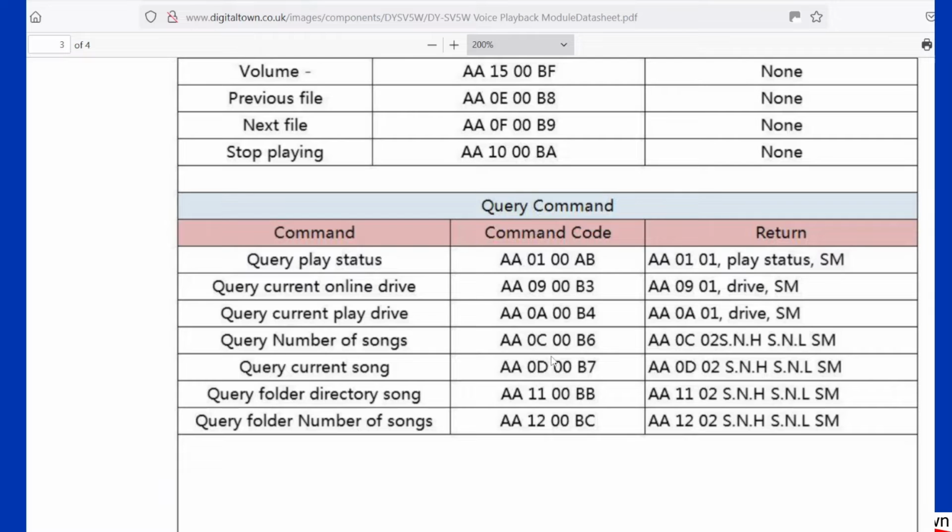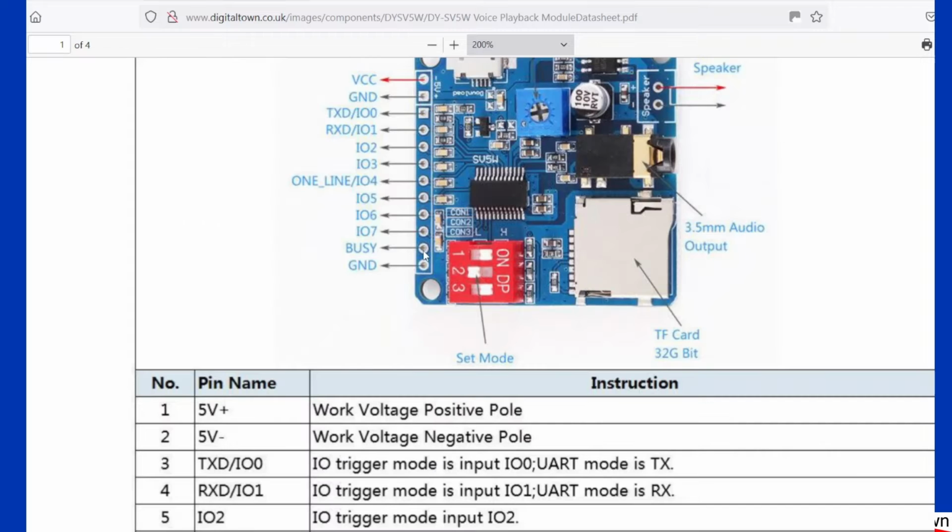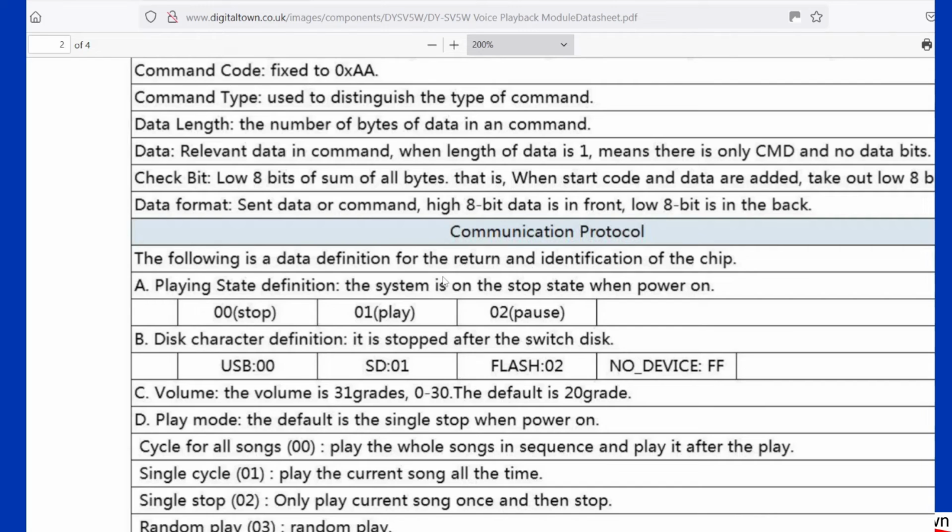playing, and that's why, when we come back to this pin here, this is why I started to use the busy pin, because when a track is playing, the busy pin goes low, so it passes back a value of 0 when you do a digital read off that pin, and when the track is not playing, it goes high. Didn't seem very intuitive to me, but that's the way it works. Anyway, that's the main bits that we need.